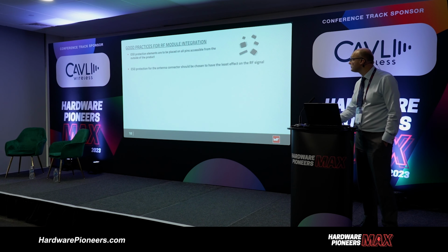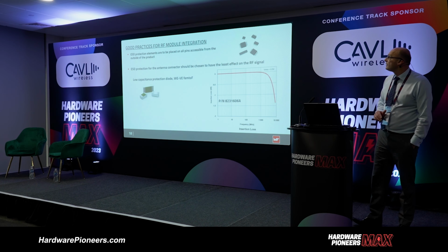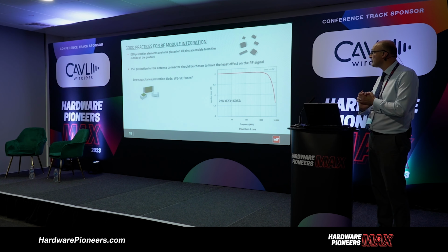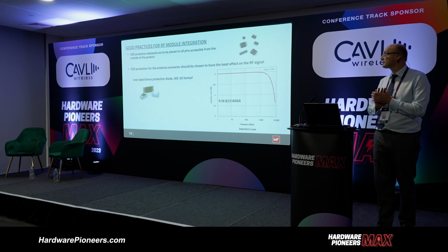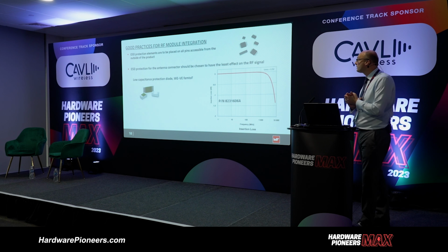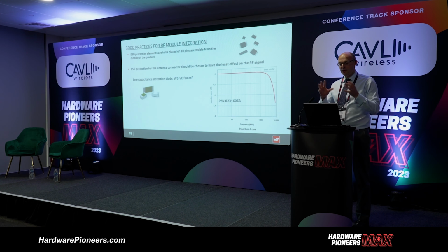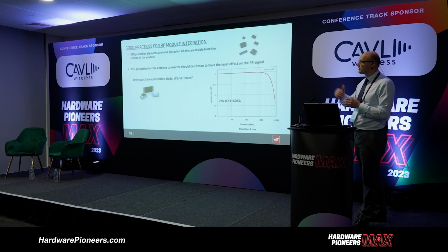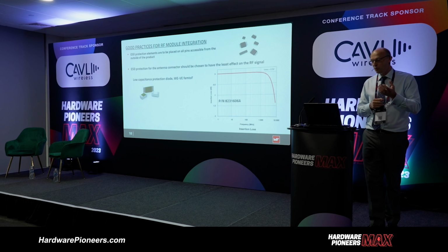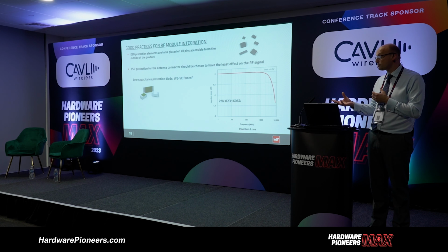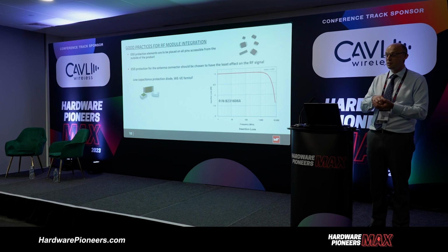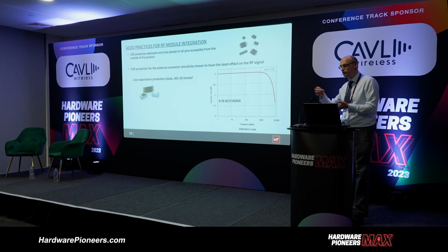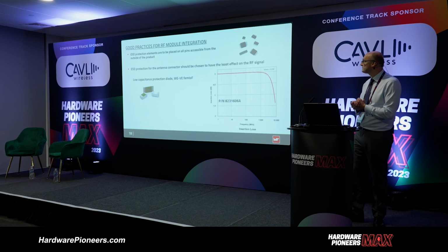Likewise, ESD protection. RF modules are quite sensitive devices. It may be that your product has accessible pins, and therefore you may want to provide a level of ESD protection, so things like TVS diodes. Another thing, if you're using an antenna port, so maybe the pre-approved module has an inbuilt RF antenna, maybe it has a 50 ohm coax, which enables you to remove the actual antenna.